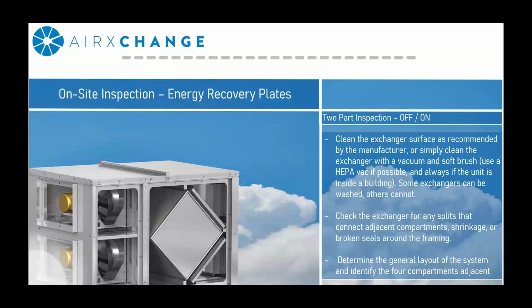After you go through that process, you're going to want to check to see if the heat exchanger has any splits in between the individual media layers, any potential shrinkage or missing sections of media, or broken seals around the frame. Anything where the device would not operate as it was initially intended. Also, once again, identify the system layout and the fan locations, so you can use that to determine the operating pressure.